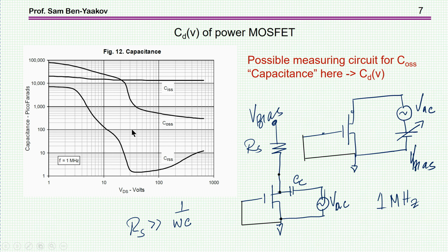So now, how do we measure these capacitances? The measurement is done under bias and with small signal. So for example, we have a bias, V bias, and we add to it some excitation. We are talking about COSS, so these two are connected together, and we look here at this drain point, measuring voltage and current, from which we can get the value of the capacitor. Or by a voltage source, this is a capacitor, so the voltage here, DC, will be like here.